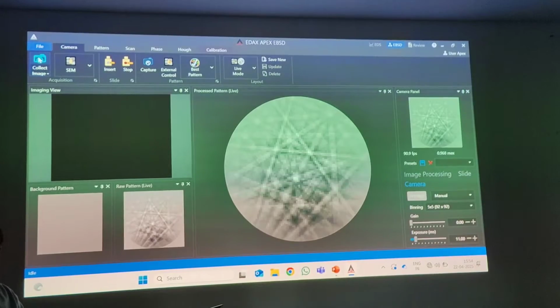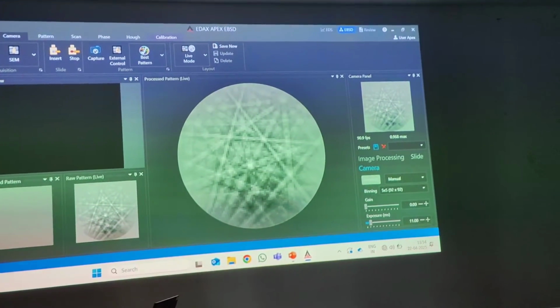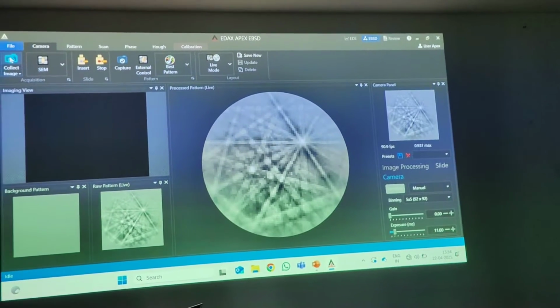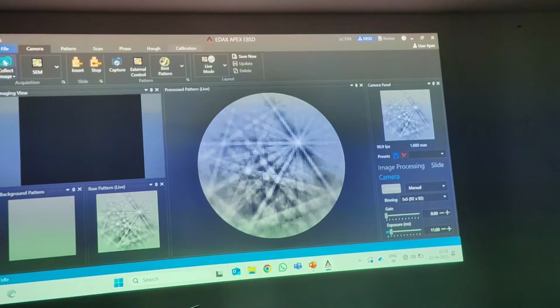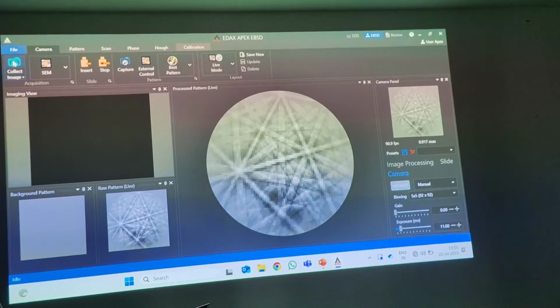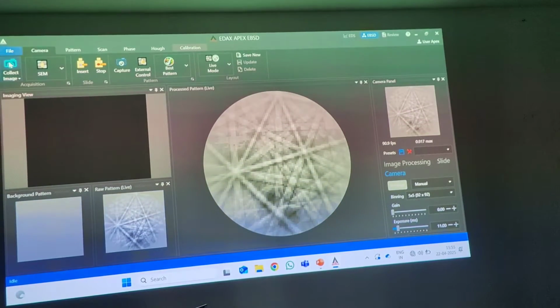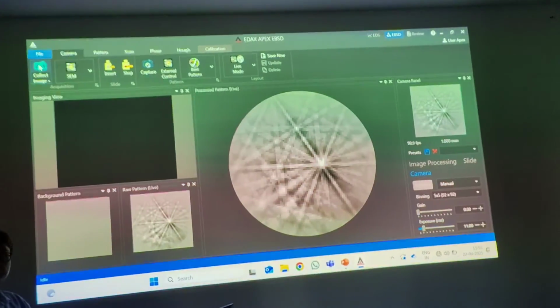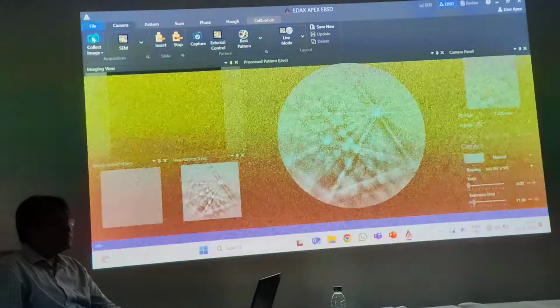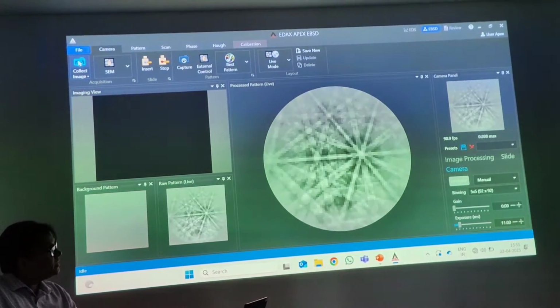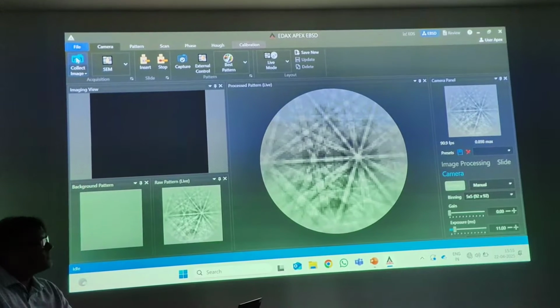And what about the beam current? Sir, 120. For EDS it is 5 to 10 kilovolt, yeah, that is true for EDS. But for EBSD, typically you need the higher kV, in the range of 15 to 20 kV. But most of the time it will be typically 20 kV. Otherwise, at 5 kV it will be difficult to generate this kind of diffraction pattern.